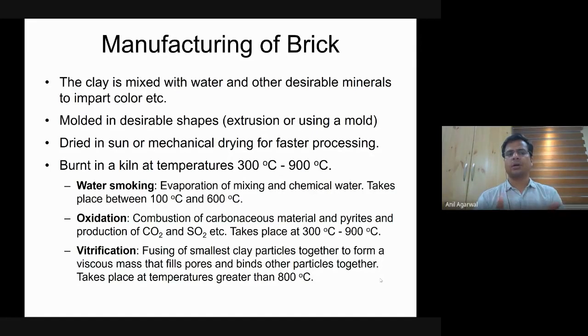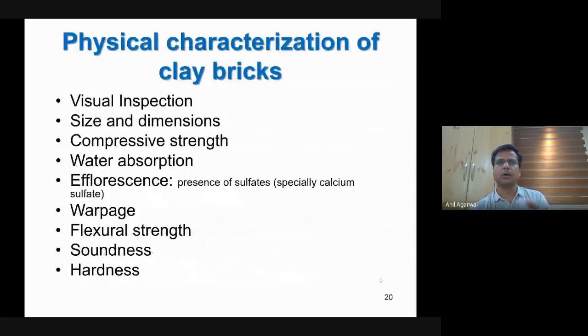Okay, so memorize this name, vitrification. You might have seen the use of this word, vitrified tiles, for example, for flooring. Often we require vitrified tiles. You may make tiles without vitrifying them, that is, you don't heat them to that high temperature, but then you don't use such tiles for flooring. For flooring, you would always use vitrified tiles. Vitrified tiles are the high strength tiles. As a consequence, you get high strength, nicely and uniformly colored bricks, free from any cracks.